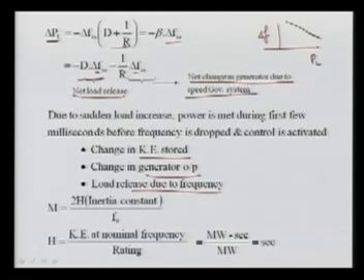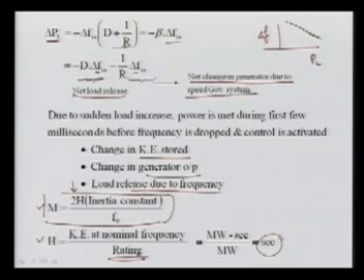Also I have related this M and H, already I have explained. This H is related, that is the inertia constant. Here this KE at the nominal frequency means kinetic energy upon the rating of the machine, and here the unit is second, and then we can also relate here. Then we have used either H, 2H upon F, or M, you have to calculate your Kp and the Tp accordingly.